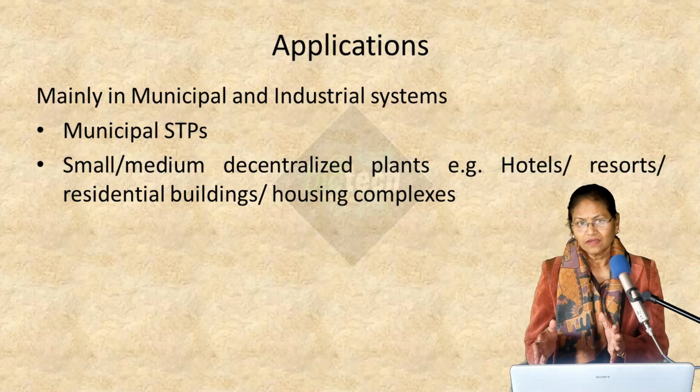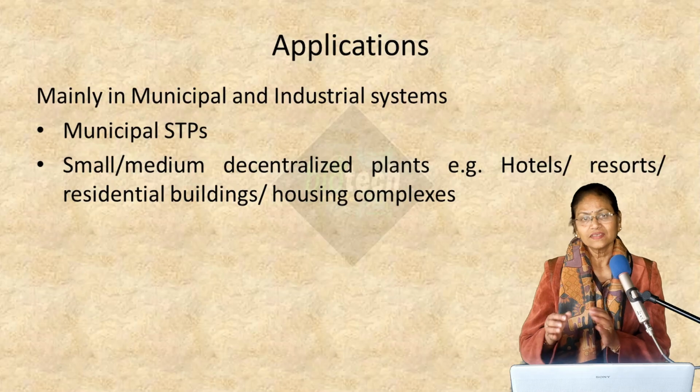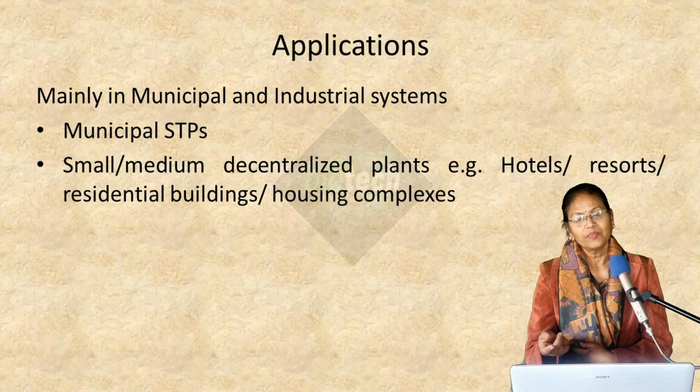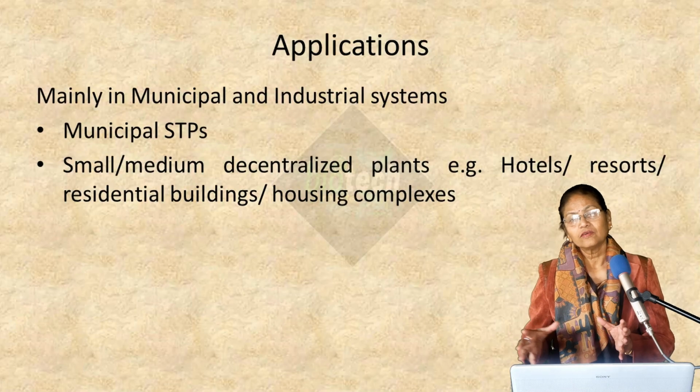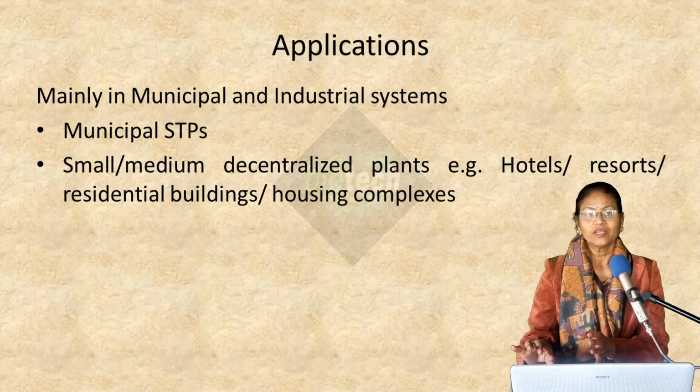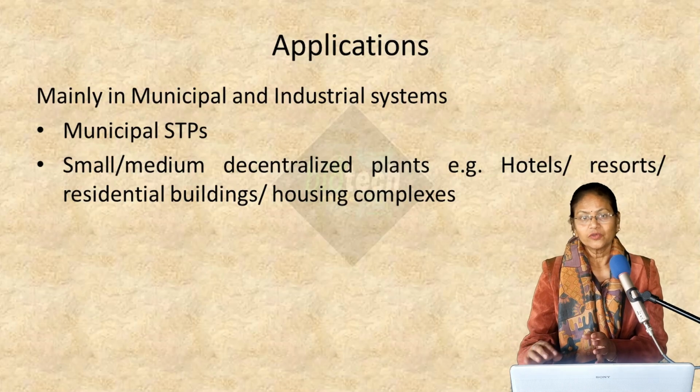Suppose there are hotels and resorts, residential buildings, housing complexes. They may have their own decentralized plants based on MBBR. So it's not necessary that the whole city's wastewater goes to one centralized place and the treatment happens only there.